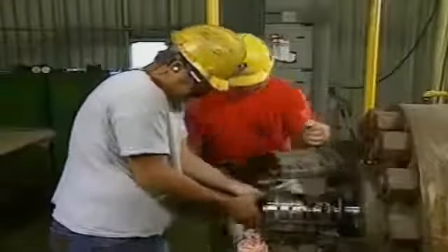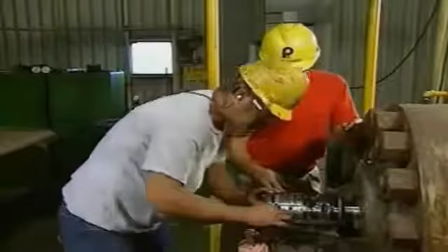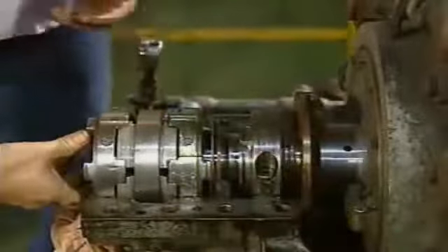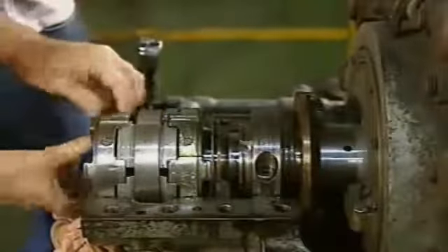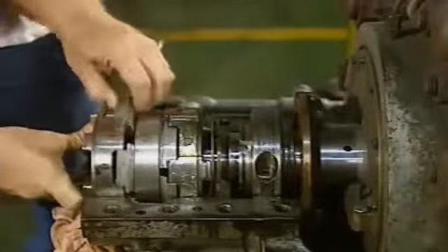The mechanic removes the end plate and the housing bolts and guide pins. He then removes the top half of the bearing housing. The outboard thrust bearing is removed first. The mechanic begins by removing the thrust shoes. The thrust shoes are placed on a clean work surface to prevent them from collecting dirt.